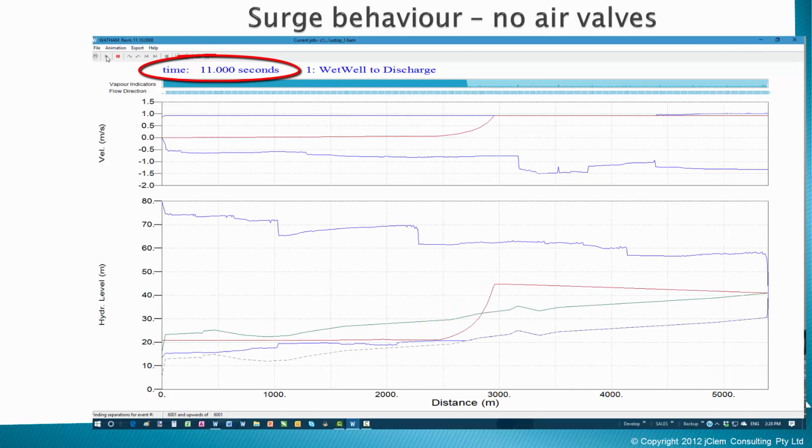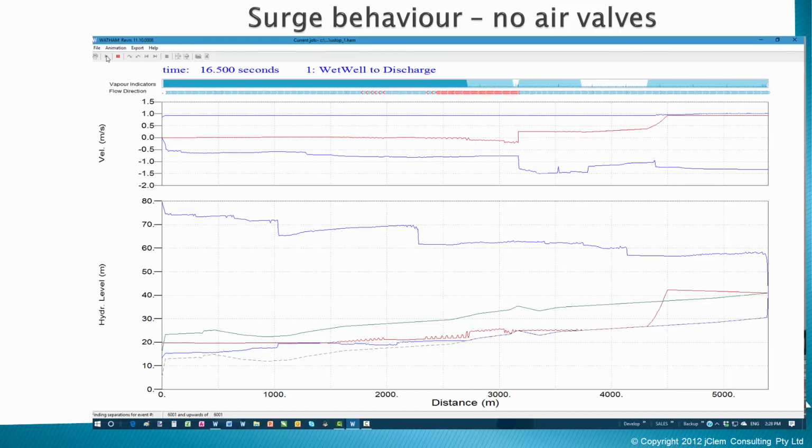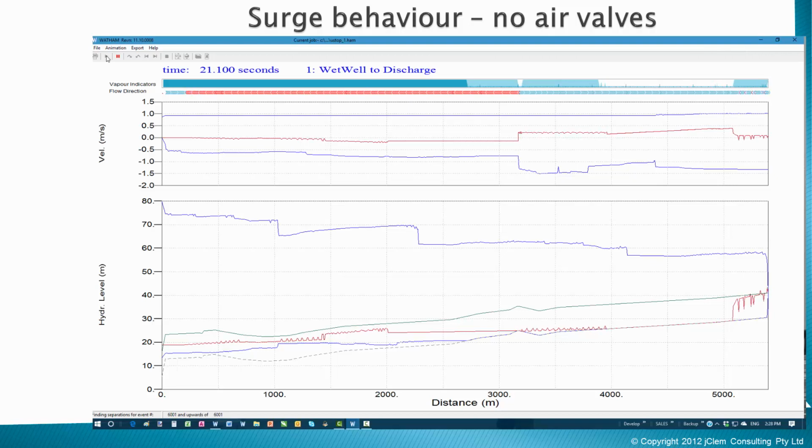Vapor head level is reached because pipeline elevation has increased. Fluid vaporizes at some locations, and wave reflection returns some locations to the fluid phase. Vaporization and fluid column separation allow parts of the pipeline to stabilize to different velocities. The downstream fluid column is only slowing to about 0.3 meters per second.